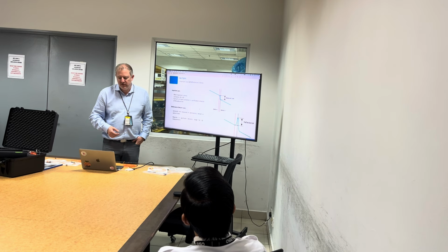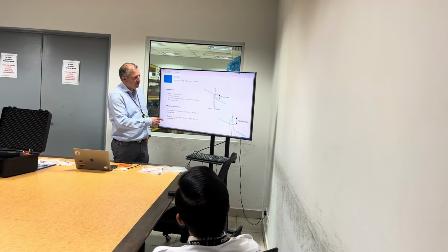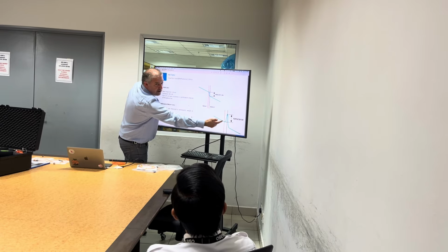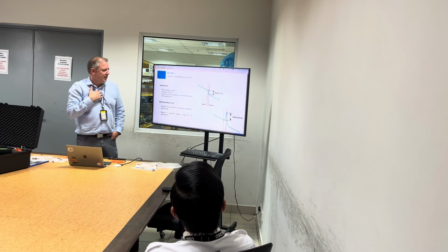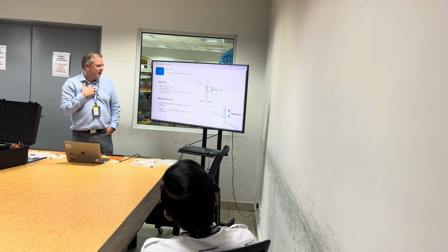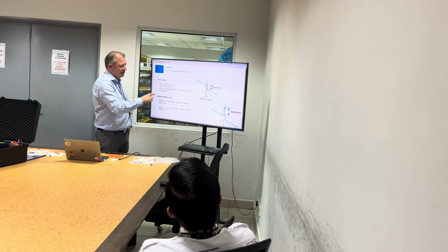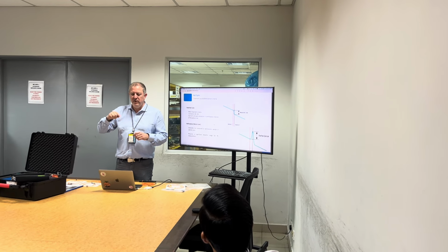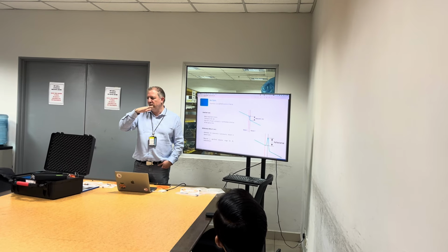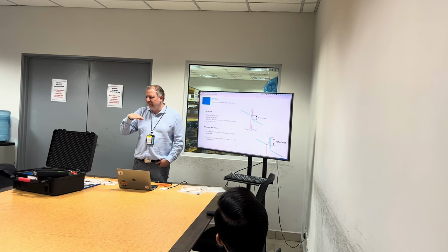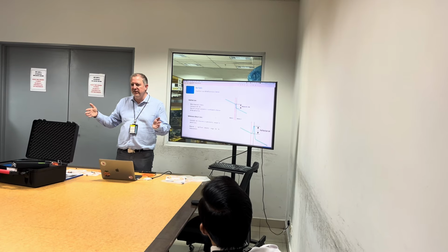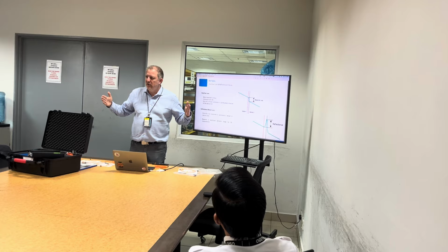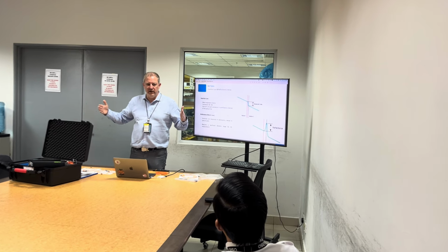So this is what I was mentioning. The insertion loss is the step you have here, and the reflectance is the height of the peak, which is there. The important thing is that if you sum the insertion loss at all the points that you have, and in theory you add that to the attenuation, which is almost zero in our case because we have such small distances, then you see the full attenuation of the line.